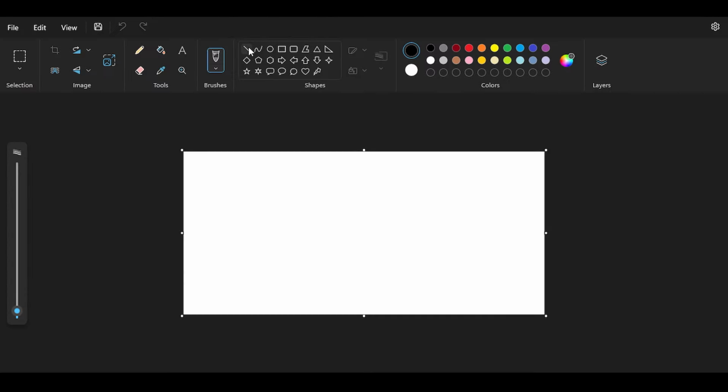I mean, this is from structures, right? Let's make a simplification. You have a beam like this that is extending or overhanging. So you have a support here and a support here, and you are interested in the moment at this point. The influence line of the moment at this point looks kind of like this, using Müller-Breslau's principle. That's the influence line of the moment at this point.